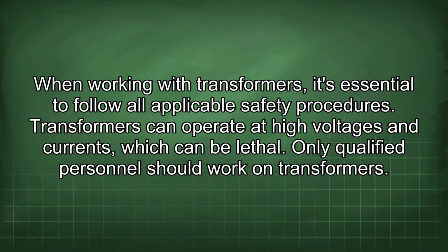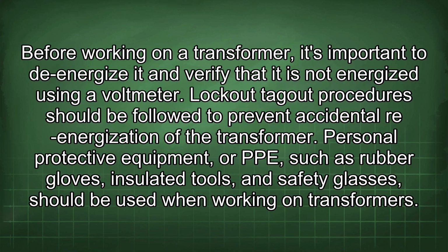When working with transformers, it's essential to follow all applicable safety procedures. Transformers can operate at high voltages and currents, which can be lethal. Only qualified personnel should work on transformers. Before working on a transformer, it's important to de-energize it and verify that it is not energized using a voltmeter. Lockout-tagout procedures should be followed to prevent accidental re-energization of the transformer.